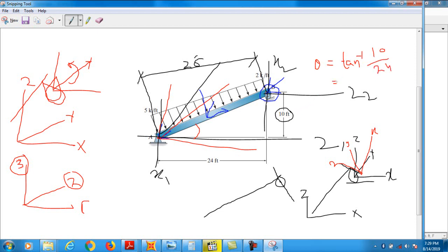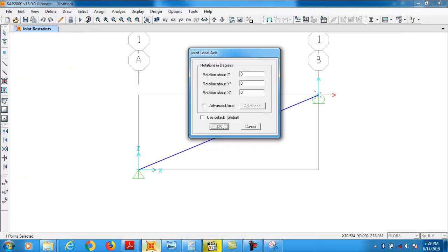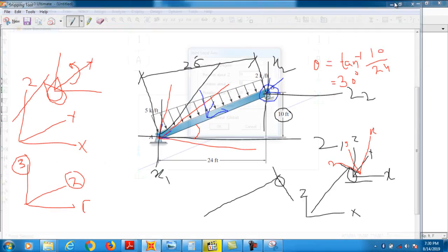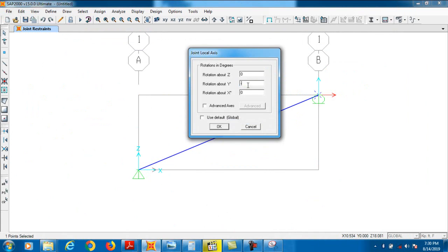Its roundabouts comes out to be, I think so, 30 degree. Clear? So this will be around about 30 degree. Clear? So let's see how we will rotate. Now the rotation is about y-axis. And one thing you must clear, that the rotation basically starts from z-axis, or you can say x-axis. So we have to rotate it anti-clockwise, not clockwise, anti-clockwise. So therefore we insert a negative angle.